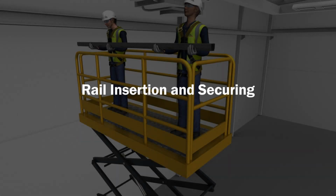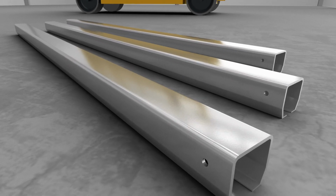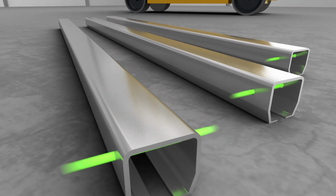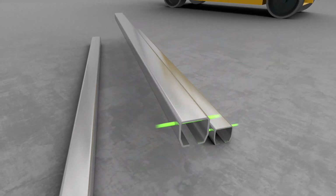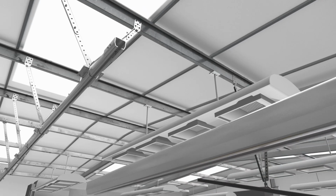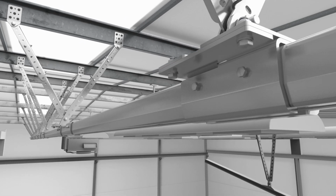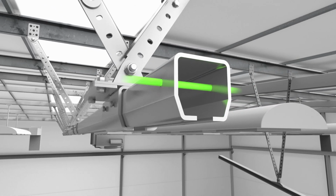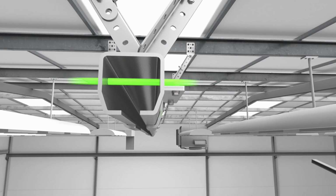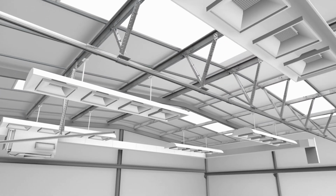Rail insertion and securing. Each section of rigid rail comes supplied with a single pre-drilled 9/16 of an inch end stop buffer hole. For all extremity positions, it is imperative that the rigid rail is orientated to ensure the end stop buffer hole is in the correct position, where the rail terminates. For all intermediate rigid rail sections, the end stop buffer hole position is not critical.